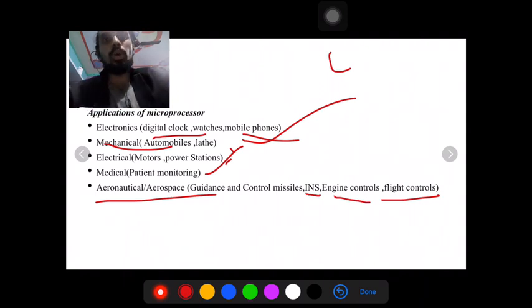Okay, let's go in detail. So RAM. Basically whatever you are performing on the CPU, or the program that you are running, will be stored in this memory. So it is volatile. That means as soon as the power is gone, the data will be lost. Again, I can classify it into static RAM and dynamic RAM. Static RAM is going to hold its contents as long as power is available. But DRAM, you need to recharge it every few milliseconds.